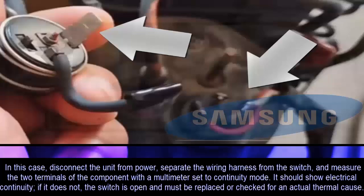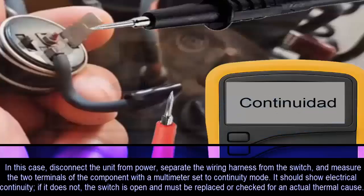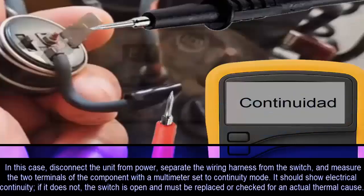In this case, disconnect the unit from power, separate the switch wiring harness, and measure the 2 pins of the component with a multimeter set to continuity mode. It should show electrical continuity. If it does not, the switch is open and must be replaced or checked for a real thermal cause.